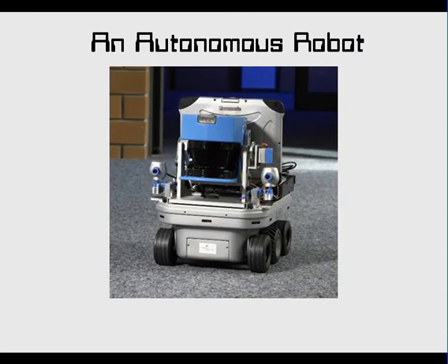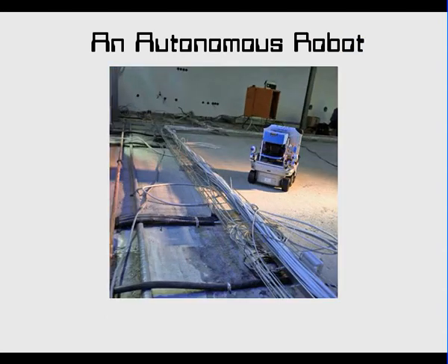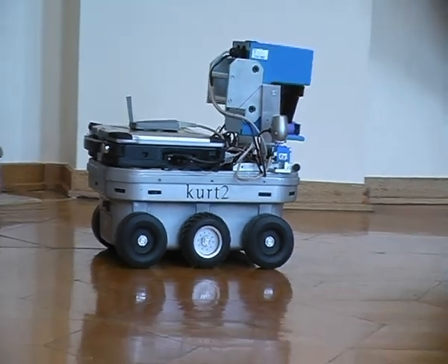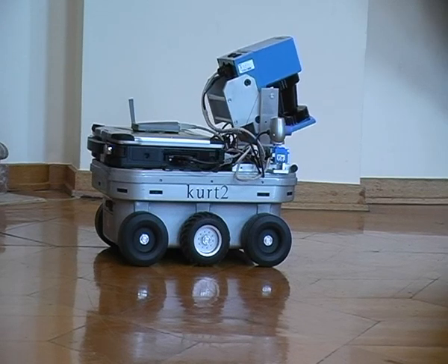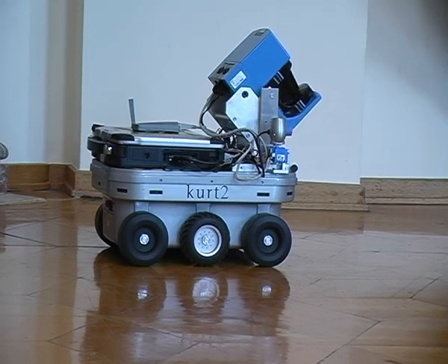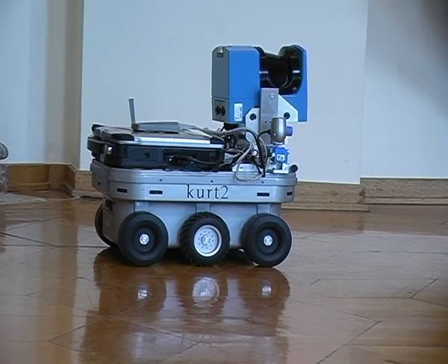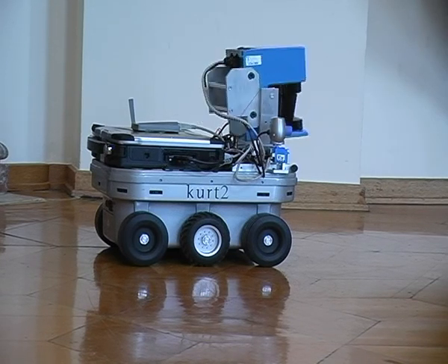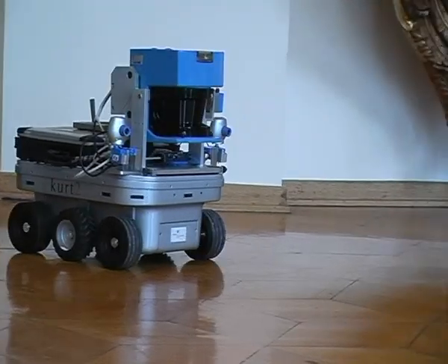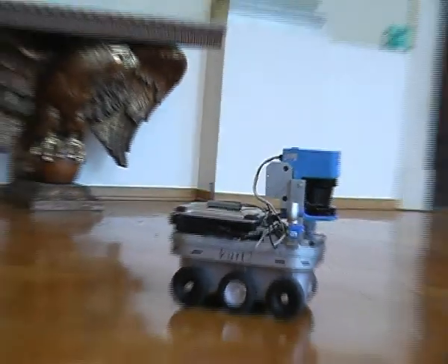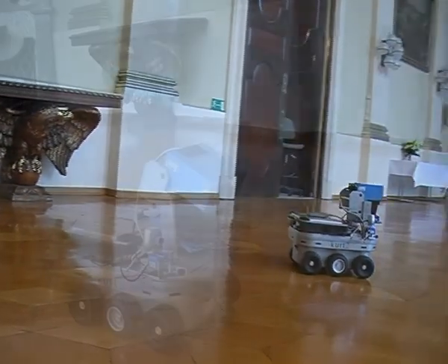Developed at Fraunhofer AIS, Kurt 3D is an autonomous robot that is commercially available. A Pentium 3 notebook and a C167 microcontroller drive the robot. 2 90-watt motors are used to power the 6 wheels. Front and rear wheels have no tread pattern to enhance rotating. Here we use a controlled velocity of about 1 meter per second. Traveled distance is measured by odometry and scanner.